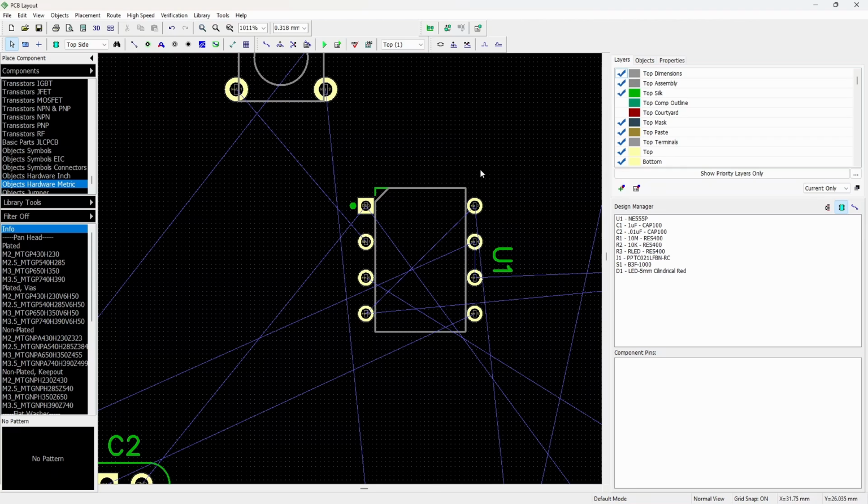So let's look at what these layers are. I can show all layers, and I can turn different layers on. If you search for all Eagle layers explained, Eagle is another EDA software, there's a list of all the different layers that are in Eagle. They're essentially the same as the layers that are here, because our end game here is to not have a net list like we are with Schematic, but to have Gerber files. That's what we get out of this, is Gerber files.